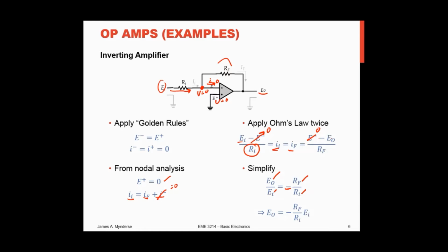Okay, so basically, as an operational amplifier in a computer, now I'm doing multiplication and division based on the ratio of those two resistors, and if I wanted to make a programmable multiplier, I could fix one of these resistors, put a precision potentiometer in place of the other resistor, and then I just turn that potentiometer up and down to get the multiplication constant I want to use.